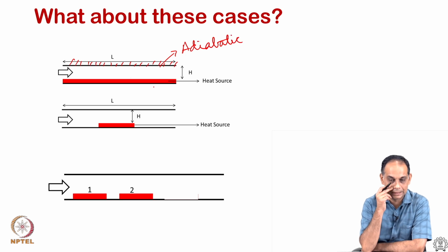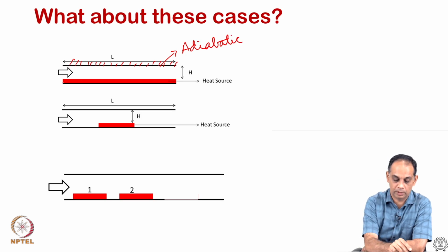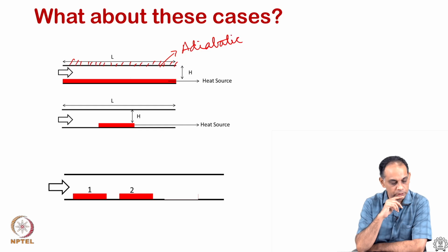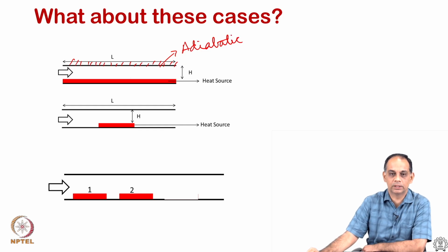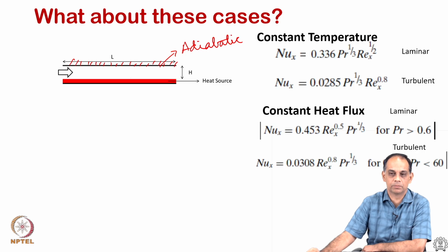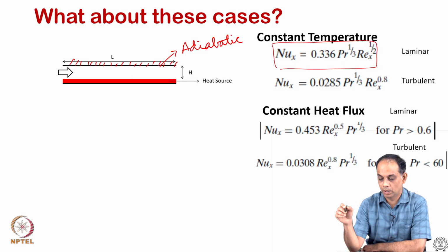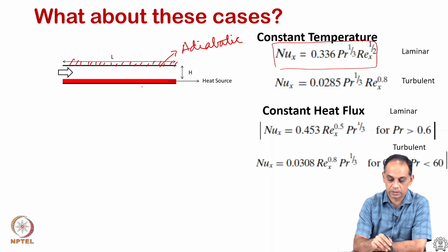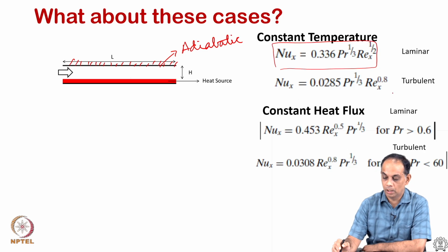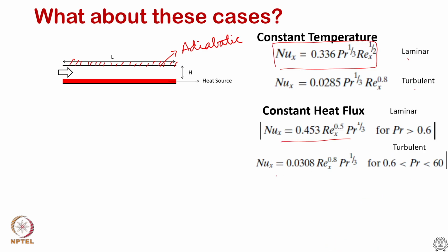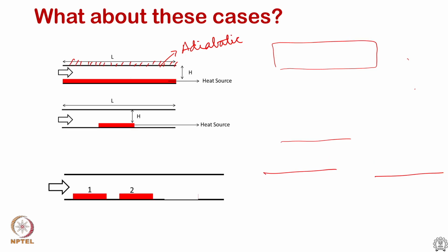And the bottom wall is dissipating a certain heat flux, a uniform heat flux. And if I say the flow is not going to be fully developed, so what can I do? This also can be treated with simple constants, and I am going to use this expression to obtain the constant temperature if the wall is constant temperature, or constant if it is laminar, turbulent, if it is constant flux, then we have so many possible scenarios of dealing with.